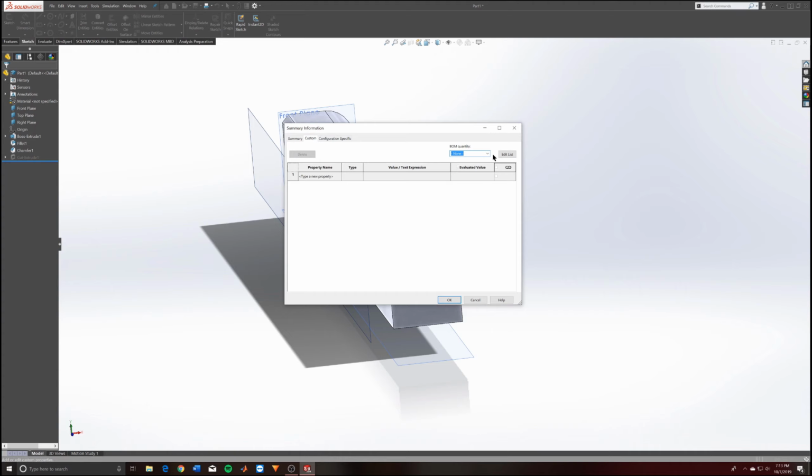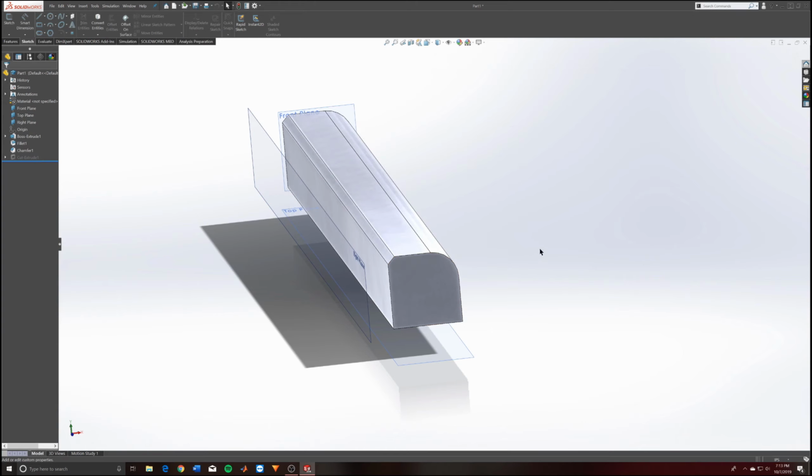And this is where you can actually see your different configurations, where you have your hole version and your default, and you can change configurations and whether it's in the bill of materials and things like that. Pretty cool, and it helps down the road when you're making your drawings and you want to quickly and easily change and modify your drawing names and titles.